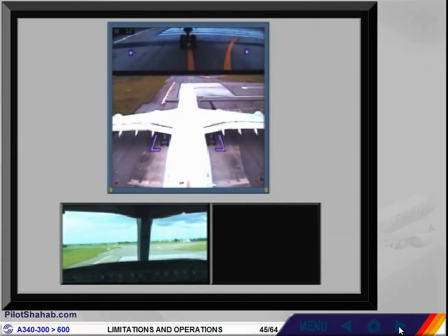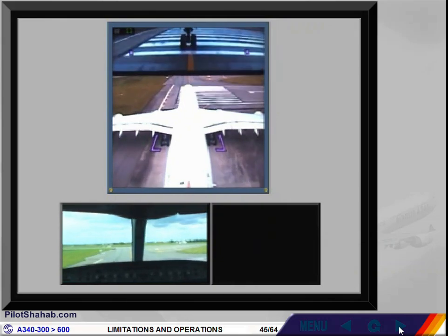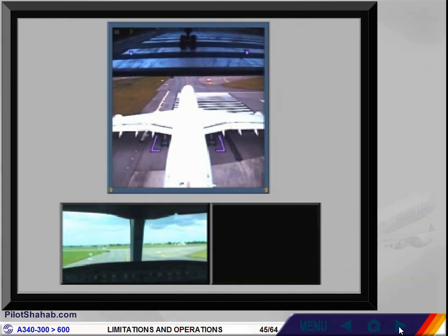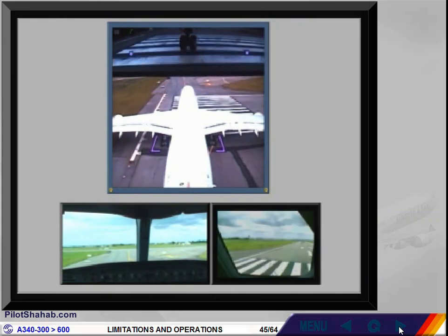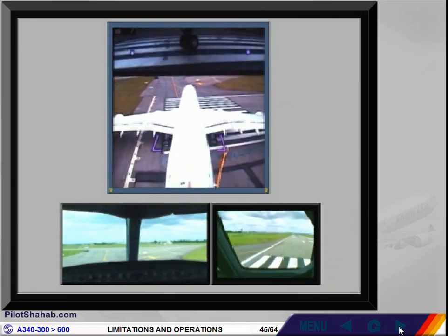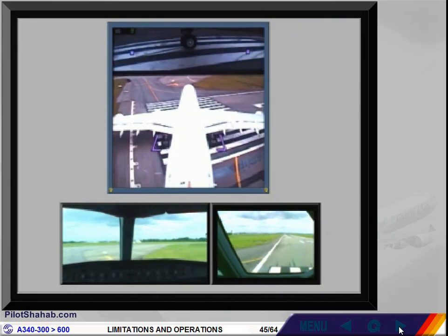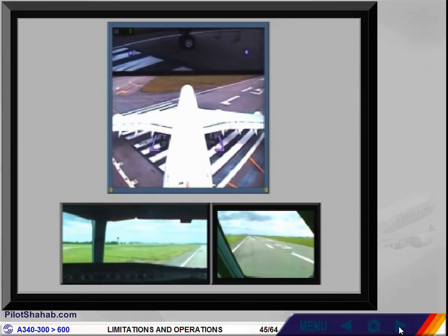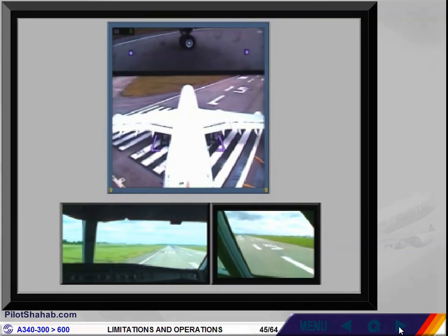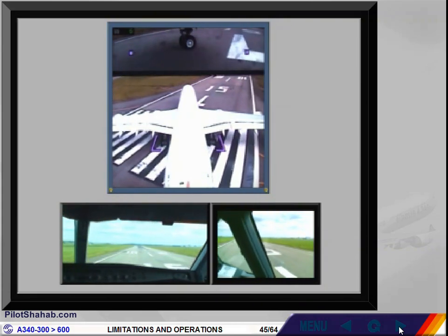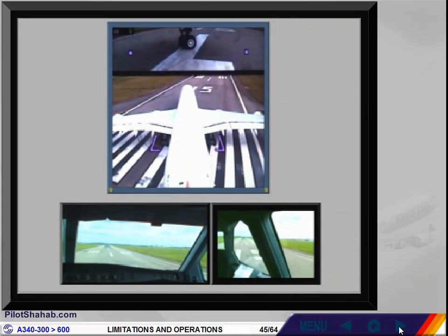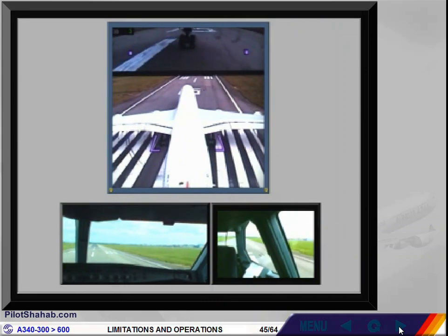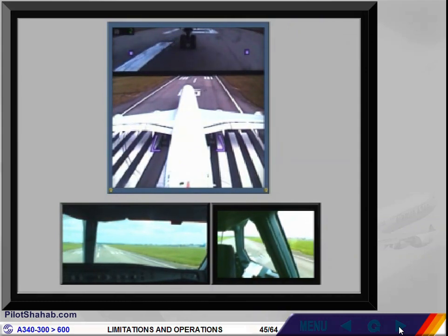Notice that for any alignment, oversteering technique must be amplified in order to minimize the amount of runway used. Note, takeoff performance computation takes into account 25 meters, 82 feet, TODA, for a 90 degrees alignment, and 61 meters, 200 feet, TODA, for a 180 degrees alignment.